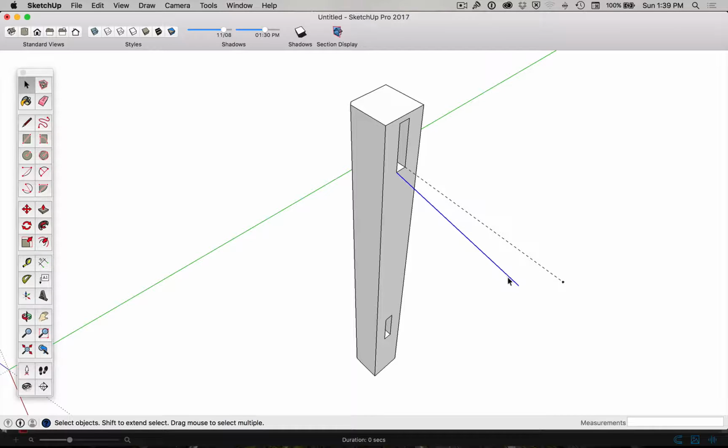What I want to do, let's get rid of this confusing line, is start drawing our tenon here. The reason for that is I'm going to show you how we can join two parts of geometry. So we're going to have an apron that's going to slot into here exactly. The shoulder, on the inside shoulder of the tenon, needs to socket right in there. All of these parts are going to be right up against each other. So I want to show you how we do that too.